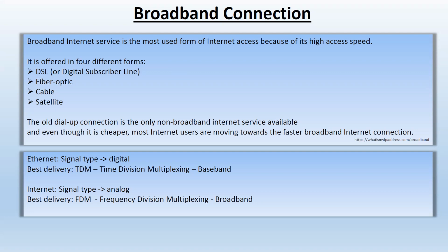Not to be confused with the hard loop. A hard loop is a diagnostic circuit, and it's used to test Ethernet links. For example, an Ethernet link using Cat5e uses 2 pairs, orange and green. One is transmit, one is receive, and it's connected to whatever device in a way that both pairs can receive and transmit signals accordingly, connected to the circuitry of one device and the other.